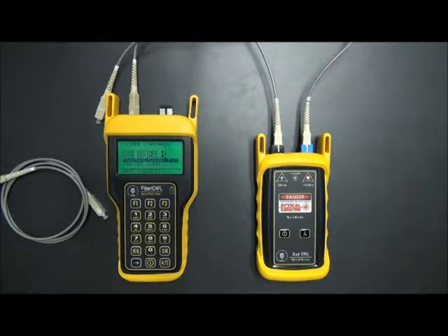The next question that we're asked to answer is fiber standards. Now there are quite a few different cabling standards in the industry today. Most of the time you will use the TIA 568, although there are other standards like this ISO standard, which is used in Europe. There are some Ethernet standards, and even if you're an advanced user, you can develop your own TIA type link budget, TIA type standard by configuring a user definable standard. But for our purpose today, we're just going to select the TIA 568.